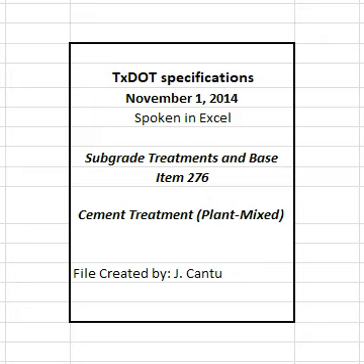The vertical face may be created by using a header or by cutting back the face to approximately vertical. Place successive base courses using the same methods as the first course. Offset construction joints by at least 6 inches. 4.3 Compaction. Compact each layer immediately after placing.